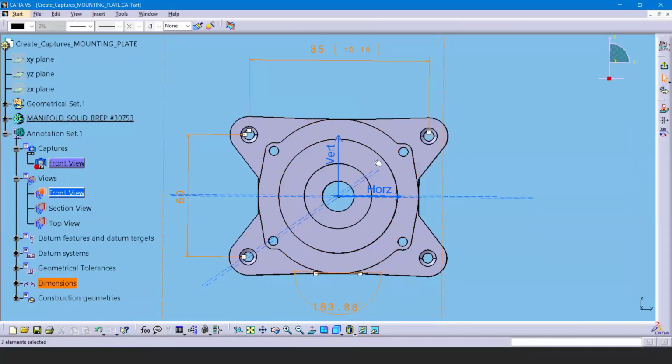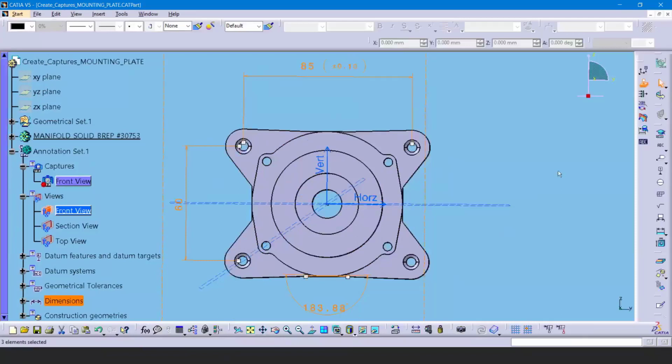And then when I click OK, notice that those little black lines, those black remnants are not here on the screen anymore. So I have successfully set up my front view capture. I spun my camera around to a certain point and I cleaned up the screen. When you're done setting up your capture, this is where you're going to hit the exit button, which is very similar to exiting a sketch or workbench, or if you have created scenes in a product file, it's kind of the same deal. You're going to hit exit, and now you're back to the full-blown 3D FT&A workbench.